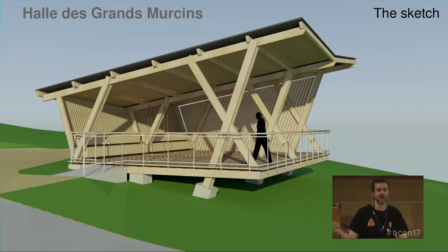Railing. Okay, thank you. And with the same curve you can use a curve modifier and an array for the vertical parts. You make the array fit on the curve so that the several array parts fit on it, then add the curve modifier, and your array follows. And then with the same curve, you just use the section of the wooden part and the metal part, and with one curve, you move the curve and everything moves.